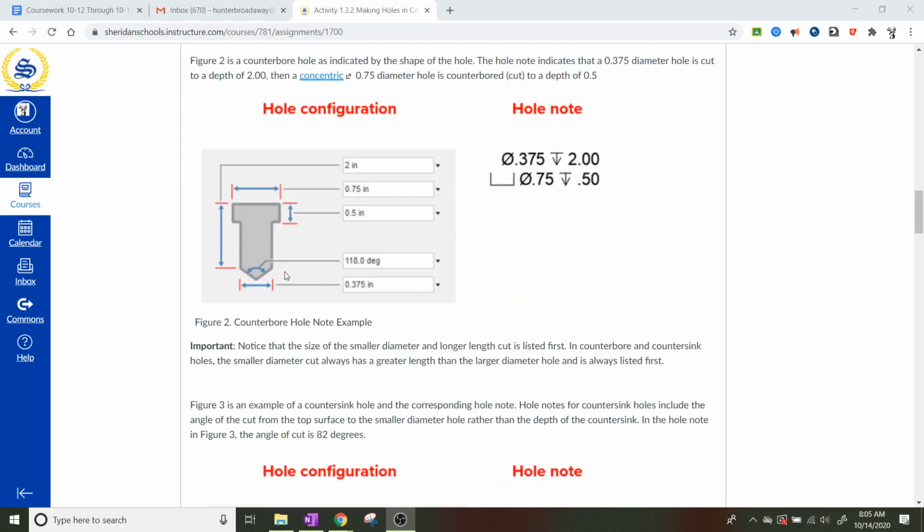The reason why there's this bottom area is because normally whenever you're making a hole, you're going to be drilling a hole. So the extra part down here is not counted in the hole depth, because every drill has this tapered end on the edge. If you were to put a screw in here, it would not actually screw in down in this bottom area.